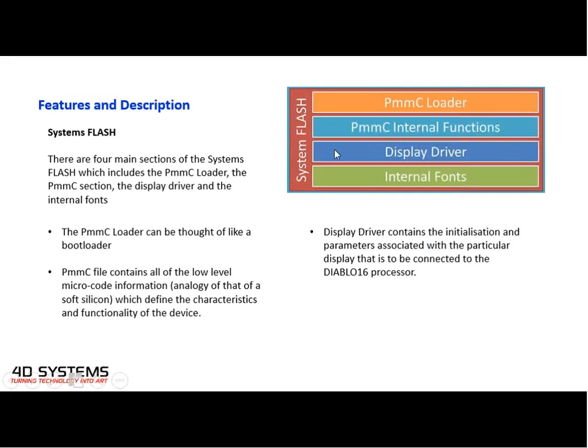The display driver section contains the initialization and parameters associated with the particular display that is to be connected to the Diablo16 processor. So the initialization and all the other parameters necessary for the display are contained in this section. Within the system flash is also a section for the storage of internal fonts. So this is what is inside the system flash.